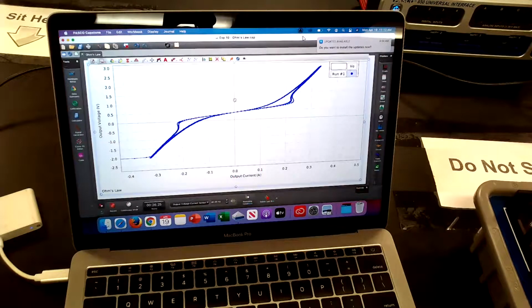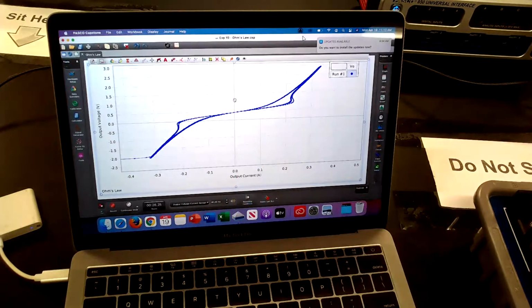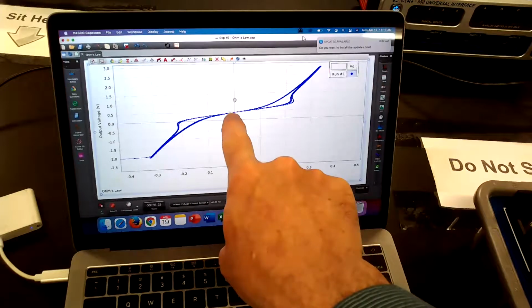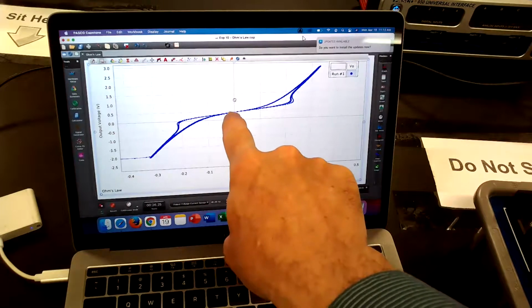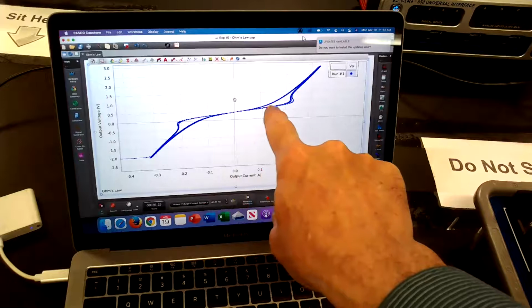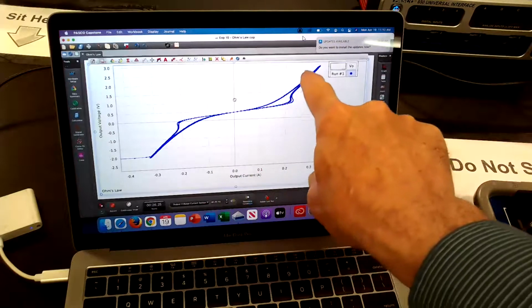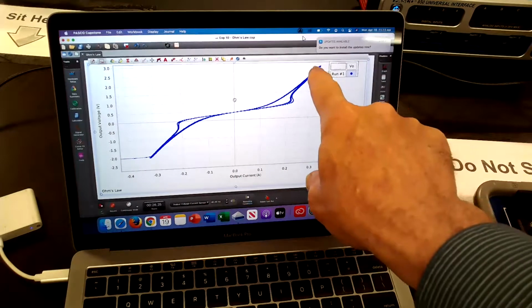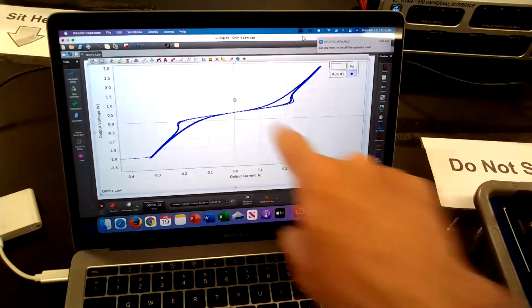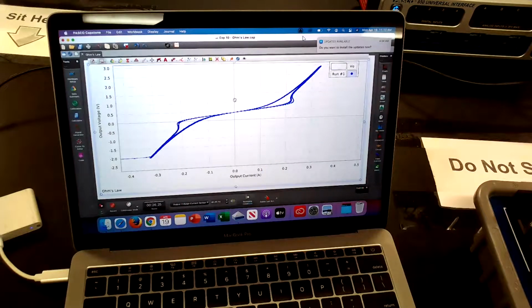look at what's going on here. Let me see something that I can use to point it. Again, that's where everything is zero. So what's going to happen here is it's cold, cold, cold. It heats up. It jumps up as the filament gets warm. And as we come down, it's cooling off. So that's why you see that hysteresis effect.